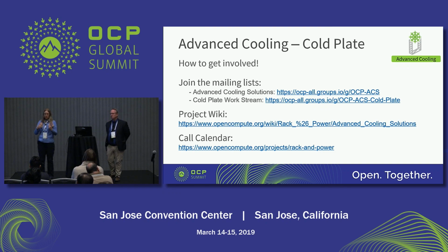What we can contribute is what we have done: here are the supplier names, here are the wetted materials that we work with, and here are the suppliers for CDUs and cold plates that we've been working with, because we have done the testing. And anyone else that has done similar testing for dielectric fluids or for water with additives and can provide similar information, that's more than welcome.